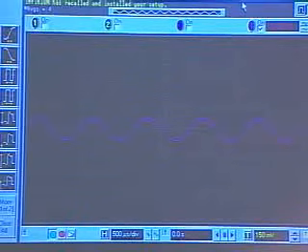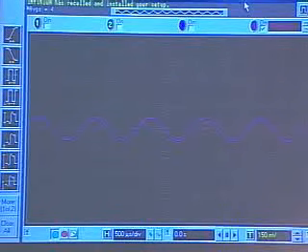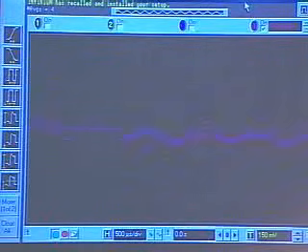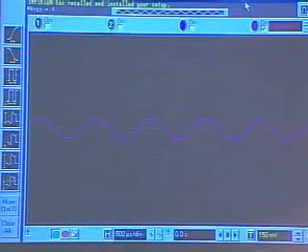Okay, so you roughly get, what's that? 10 millivolts. Okay, so it's about 10 millivolts peak to peak out there. And notice that, let's say that if the waveform rises on the left-hand side, it's positive. So it's positive 10 millivolts. And another positive 10 millivolts, so that's 20 millivolts. And this time it's a negative, roughly 20, I guess. Negative 20. So I'm getting, in terms of currents, a positive 10, a positive 10, and a negative 20 that adds up to 0.